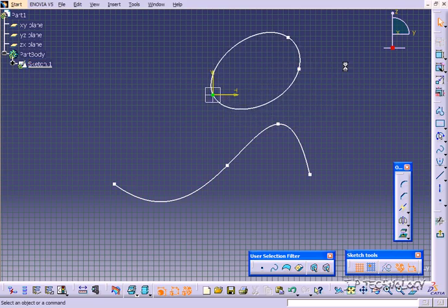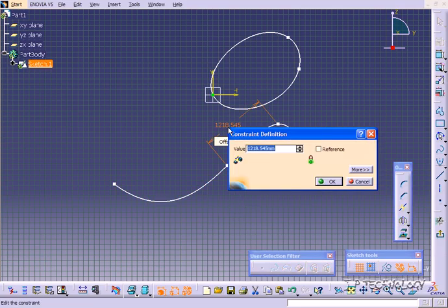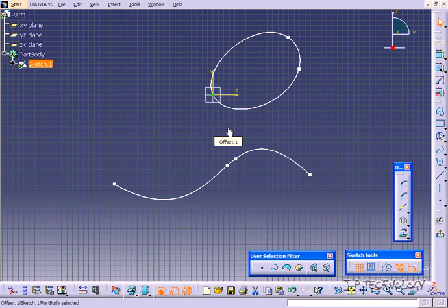Now, before I showed you that the spline tool is very mathematical, and that each of these sections is a different function, you're also able to add dimensions and constraints. So let's click Constrain, and let's click this point here and this point here, and we'll change the distances. So let's make this 2,000, or sorry, that was 200.